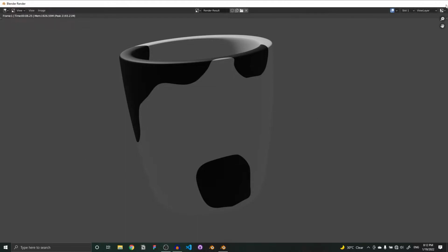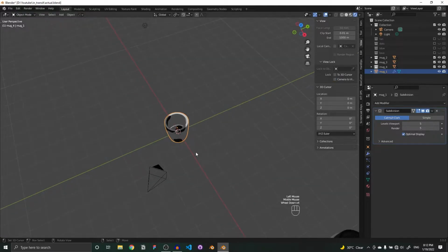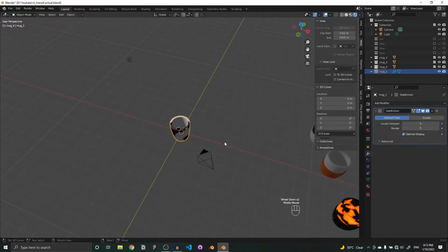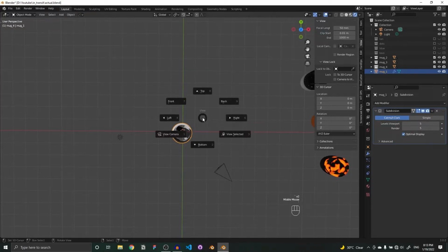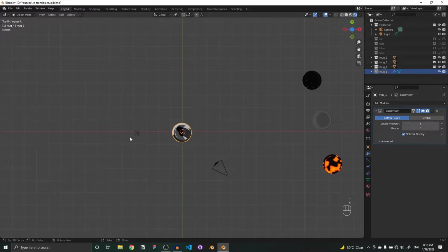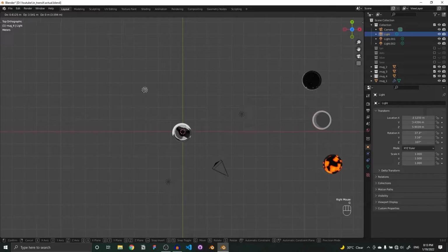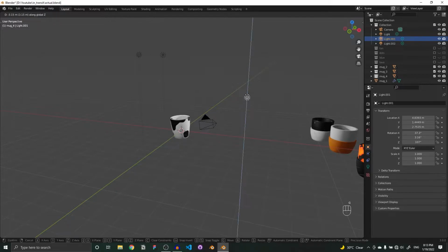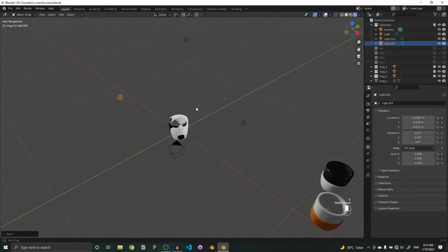We need more lights. So let's just remove this tick and then use the middle mouse button to just drag it along. Now there's only a single light at the moment, so we are going to use 3 to 4 lights. So go to tilde, top view, and select the light. Shift D, bring it to the front. Shift D, 1 to here. Select this one, G, and move it over here. Alright, so I'm going to bring it down, G, Z, and G, Z.